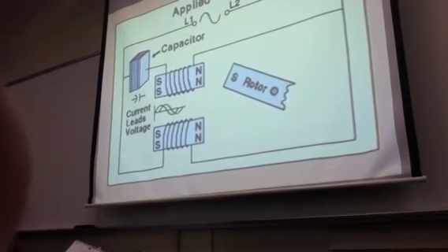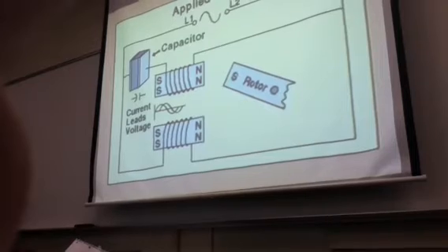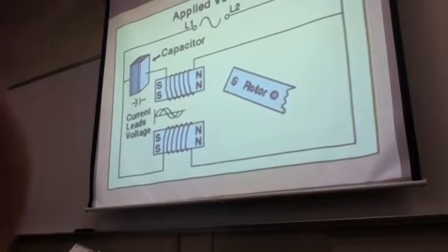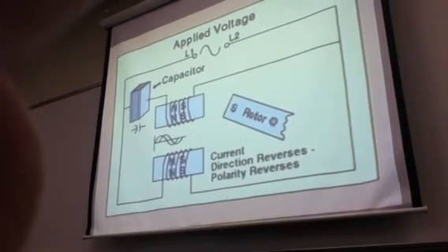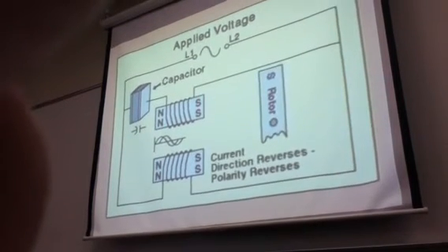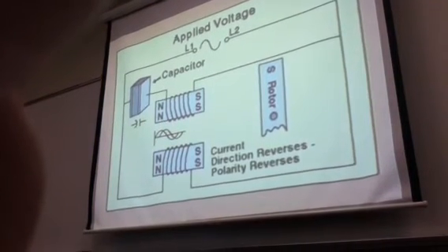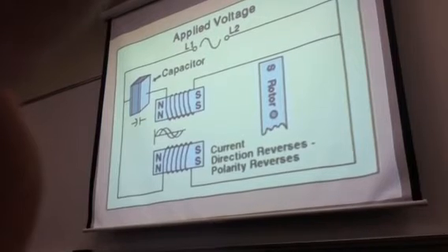When the current flow in the upper winding reverses direction, the polarity of the stator pole also changes. The rotor south magnetic pole has rotated to the point where it is repelled by the stator south pole, causing continued rotation.